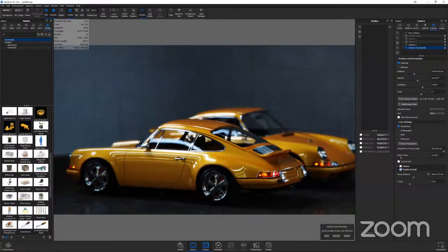So we were able to do that with hundreds of the same CAD model, and just by the click of a switch and selecting all the CAD models that we needed, we were able to generate new, fresh KeyShot files for each of these products, and then do a small, quick render of each one to make sure that we could check it off on our list, that the files were all set up correctly, that the product is in the right orientation, that the materials are applied, and that the lighting is correct.